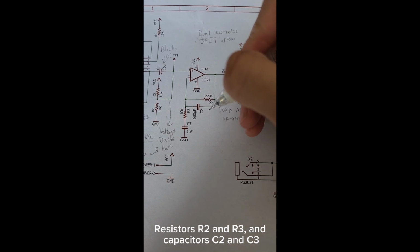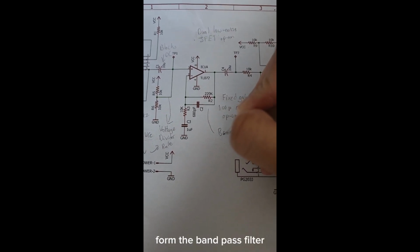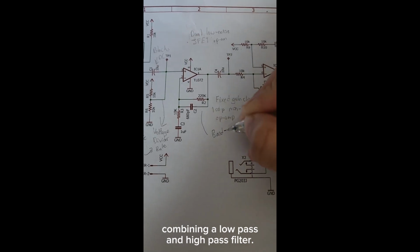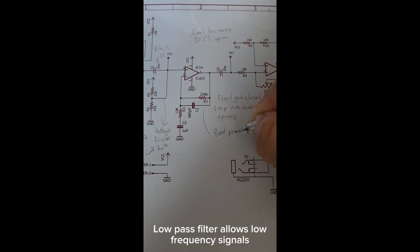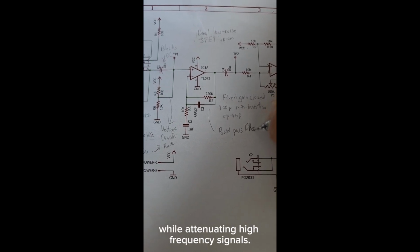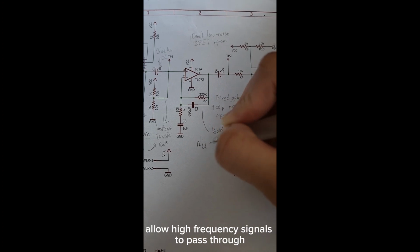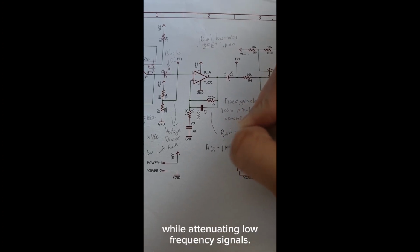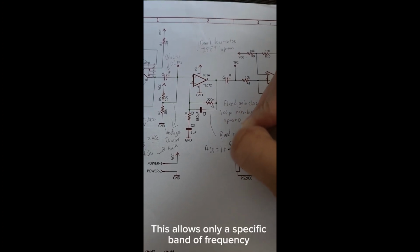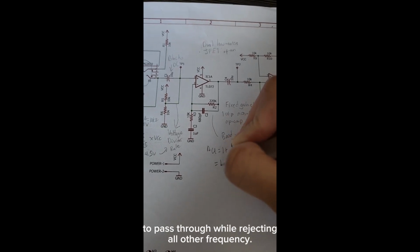Resistors R2 and R3 and capacitors C2 and C3 form the bandpass filter, combining a low pass and high pass filter. Low pass filters allow low frequency signals to pass through while attenuating high frequency signals. On the other hand, high pass filters allow high frequency signals to pass through while attenuating low frequency signals. This allows only a specific band of frequency to pass through while rejecting all other frequencies.